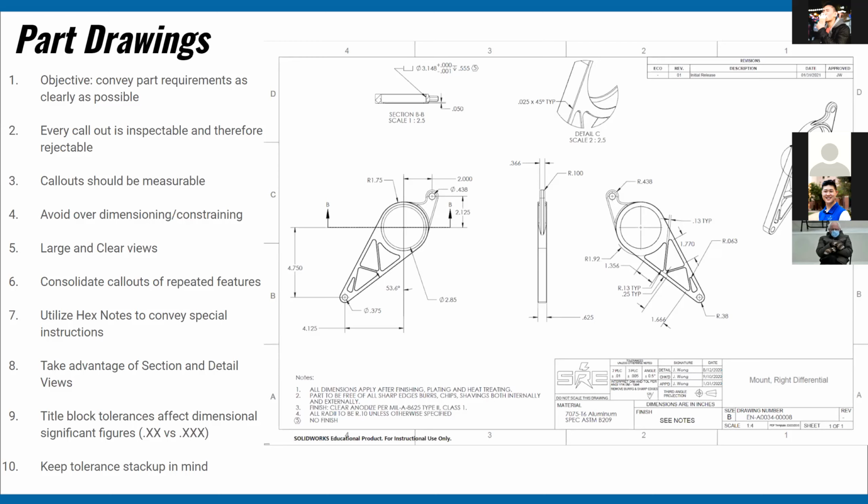And we realized when we looked at the drawing that the drawing had like a little fade of a dimension, and basically the supplier thought that was the actual dimension, understandably. And so all of that basically fed into us manufacturing an incorrect assembly. So always try to have a really clean drawing. If you keep JPEGing your drawing or something, shame on you. But yeah, just try to make sure it's readable and concise.